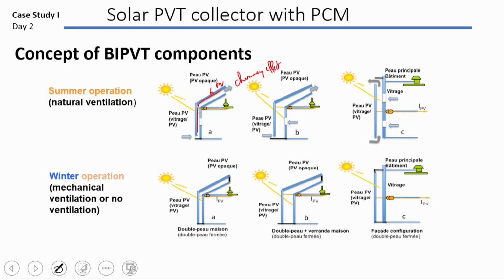Like this, you generate a free cooling of the PV envelope, and you can also use this kind of natural ventilation to ventilate inside the building. Here you have the north, here you have the south. Okay, so the cool air is in the north where there is no sun, and crosses.